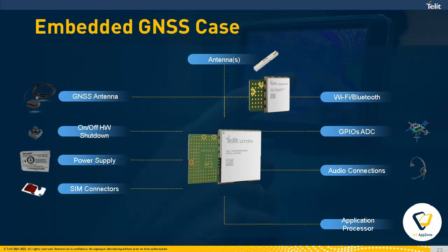Of course, that depends on the final application design, where the interference of the antennas and the antenna position and distance may reduce the need for these additional stages. If this stage is not needed on the application board, the customer may also bypass this pre-filtering stage by adding a capacitor.